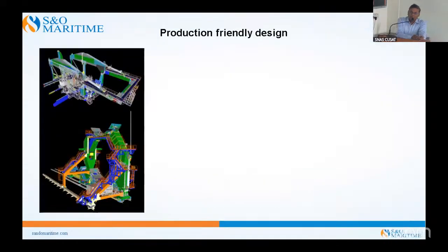Once you have that feel of how a 25 plate looks, it is very big actually, especially when it comes to weight handling, how the construction is to be done by the people, and the use of craneage. The cost is very heavy. For example, the picture in the model is something we did for a client in Europe. It's a monopile sea fastening structure for offshore wind, used to transport the monopile, the pile which is installed first on the seabed. It is transported and upended, turned upright, and lowered to the seabed.